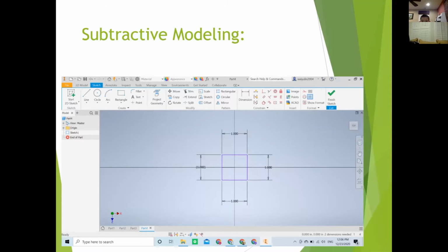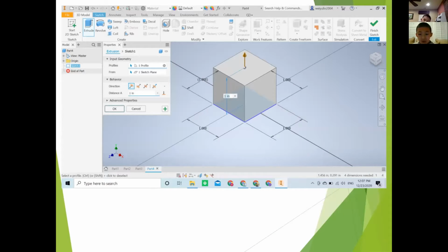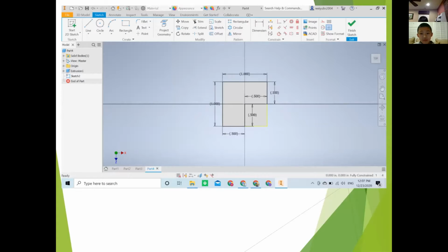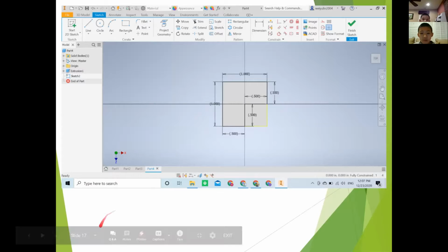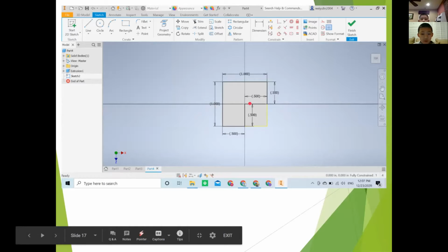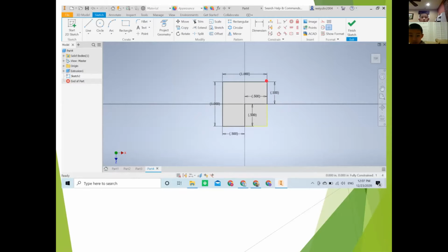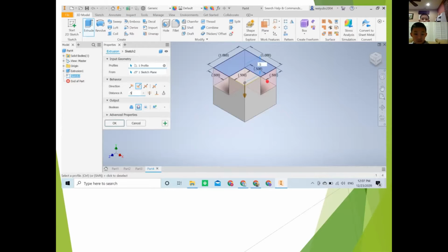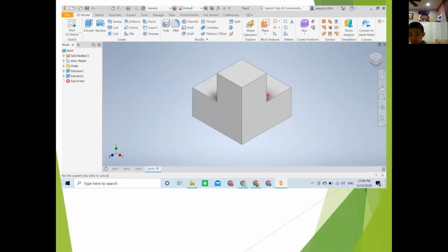So basically, we're going to build the same base. This is zoomed out a little more, but it's the same base as the first one. We're just going to make it a bit taller because we're going to dig down on it, so we don't want that little depth. Then we're going to dig out this shape right here and extrude it down. And see, you're done. You get the same shape with either additive or subtractive. So technically, these two methods give you the same result.